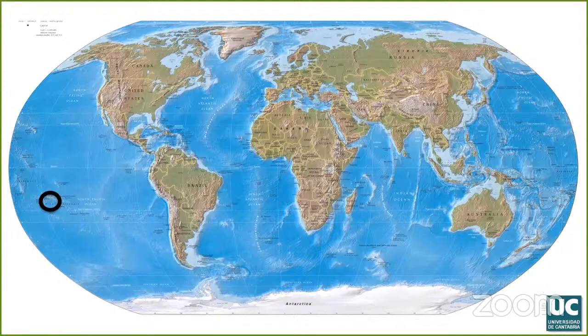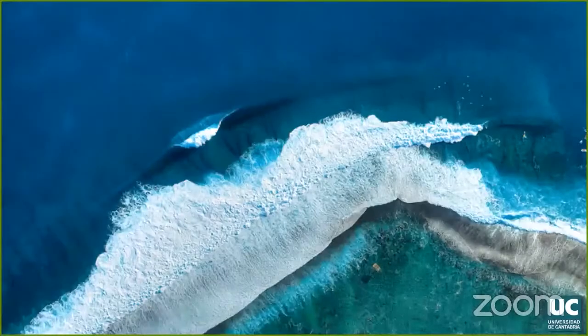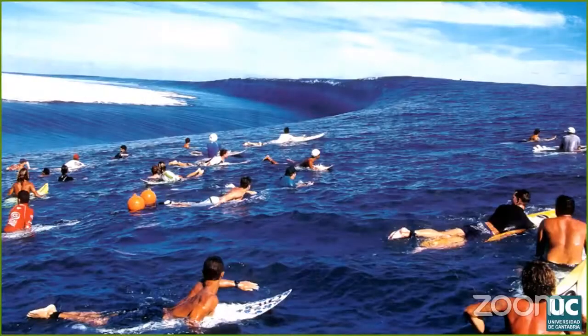In this coastal area, there is an abrupt change in water depth due to the morphology of the coral reef. This fact induces prominent and fast shoaling that in most cases ends with the wave breaking on the reef. For example, to have a rough order of magnitude of this process, a wave train with a wave height of 2 meters and a wave period of 20 seconds can be transformed into a wave train of more than 6 meters, which results in a shoaling coefficient of more than 3 units.